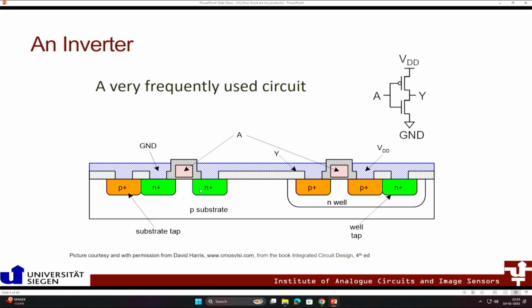And then we will have diffusion. So that's our transistor here: 2 N-type diffusions, a gate contact, and a substrate contact. Something to connect to the substrate, something to connect to the gate, and 2 diffusions. And the PMOS transistor is now sitting in an N-well, and you have metal connections. The blue lines are your metal, which are connecting between this terminal and this terminal here. So that's a single transistor.